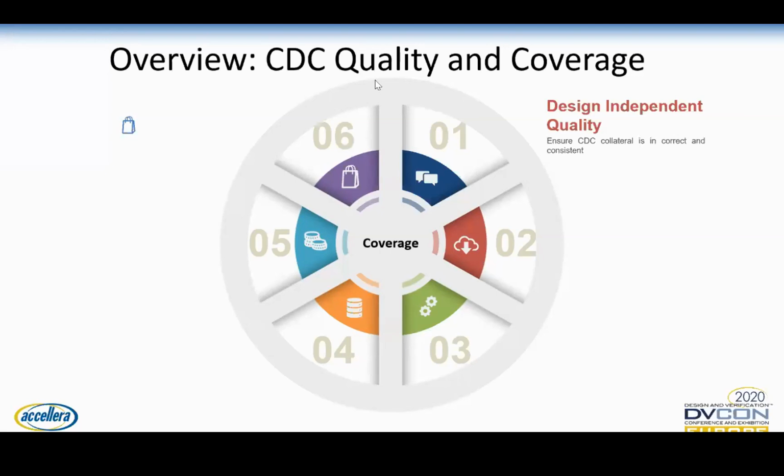When we have the abstract model or the hierarchical model coming from multiple IP vendors, internal or external, how do we ensure that when we source the abstract model in our SoC environment there are no quality issues? The first attempt is to identify this upfront, even before SoC integration is done, and ensure the abstract model quality is good enough to be consumed.